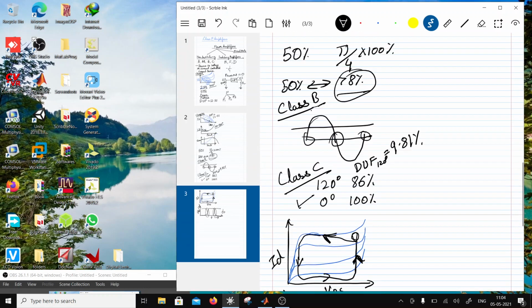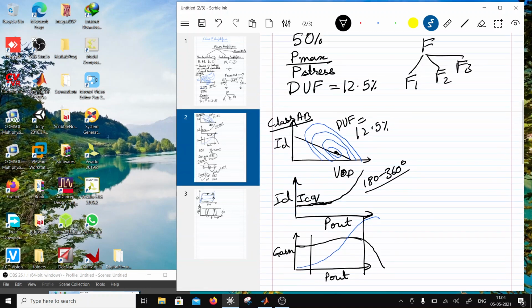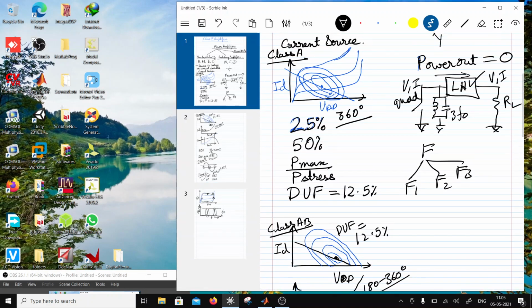Okay, so you have a square waveform of voltage and current. At the same time, you have to short out the even harmonics. So basically, if you short out the even harmonics and open out the odd harmonics, then you maintain a quadrature over here, and then the load network is going to be delivering all the odd harmonics and fundamental to the load. So what's going to happen?